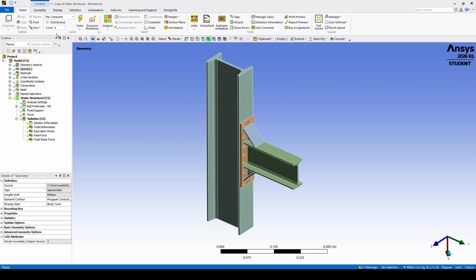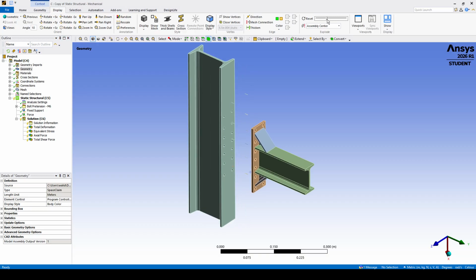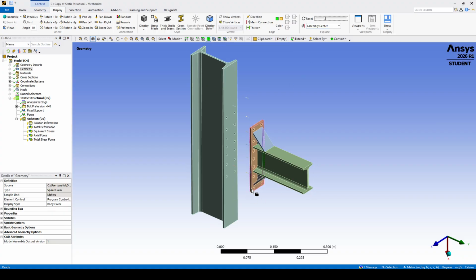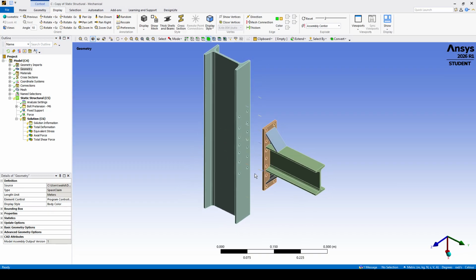you can see an important feature inside ANSYS. If you click on the geometry and go to display, there is something called explode view, and when you move this cursor, you can explode your model. What we benefit from this, not just showing that our model is exploding, is that we can also show if we have any part which is not inside the shared topology. We will see it explode alone and go off in space alone.